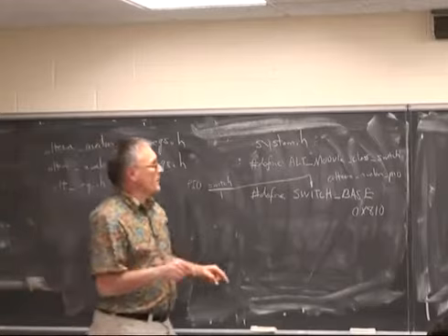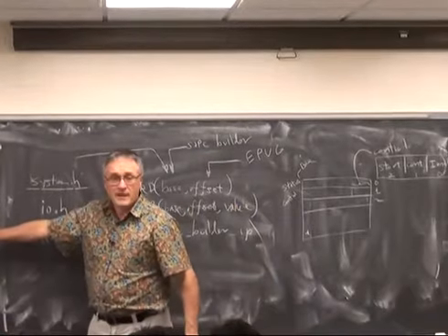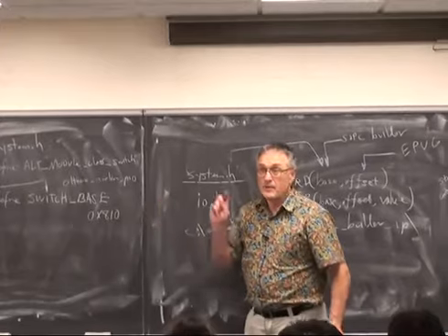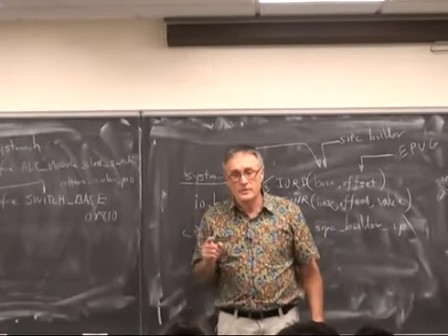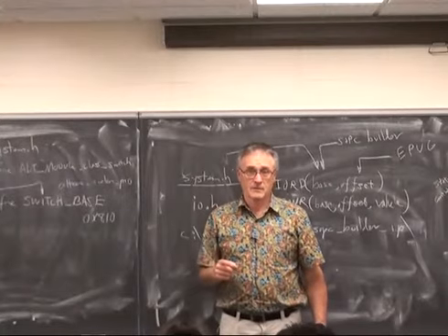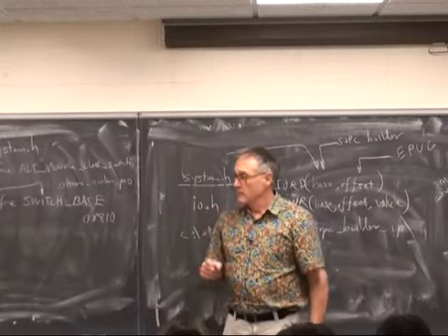When you specify the base in a read or write, you could use 0x810. That would be a bad idea, because every time you run SOPC Builder, it feels free to change the addresses. Don't do that.